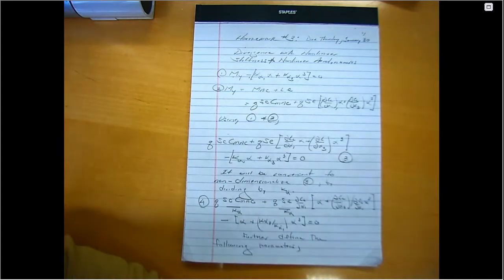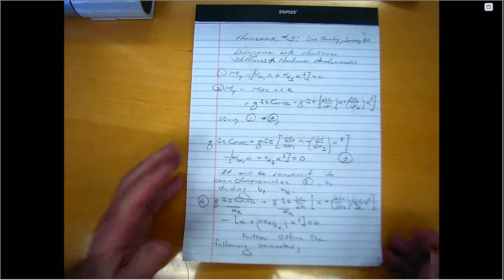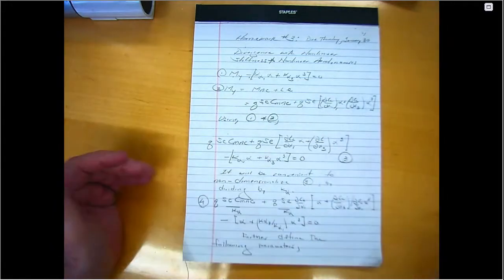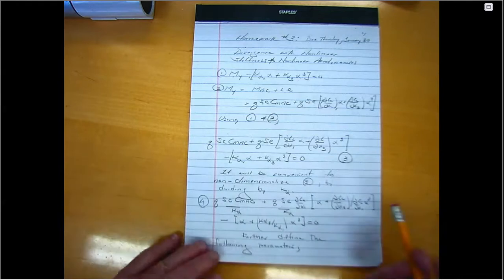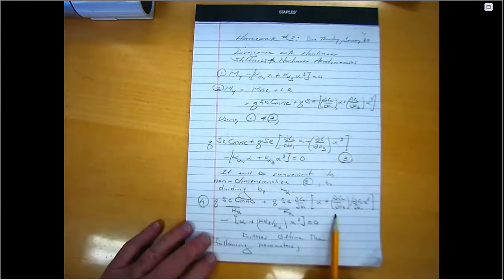Now, why do I choose k alpha? Well, because I've done this before, and I have some insight into the problem. If I were doing this for the first time, I might choose to do it a different way, and then discover after several tries that this is the better way. So I give you the advantage of my experience in that respect. Mathematically, you could do it some other way, but physically, the spring stiffness is a very basic, natural parameter to use to non-dimensionalize all these terms. So here's the non-dimensional form of the equation, and now we're going to write it more compactly on the next page.